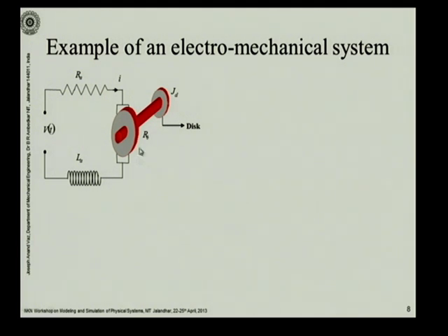And in this system, a current is going to flow through, okay, depending upon the parameters over here, the resistance, the inductance, and also on the load that is connected to the motor. And then, depending on that, a torque is going to be generated. And we are interested in modeling this. Right now, let's see how this will appear in the form of a graphic model.